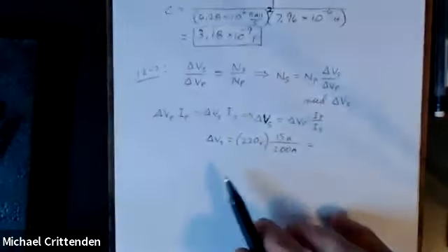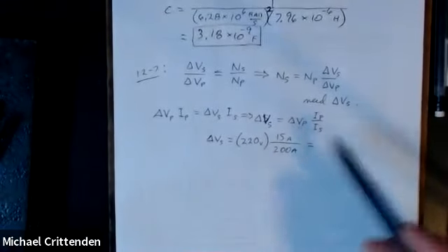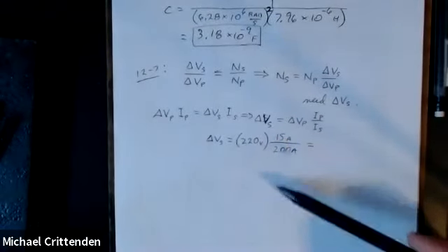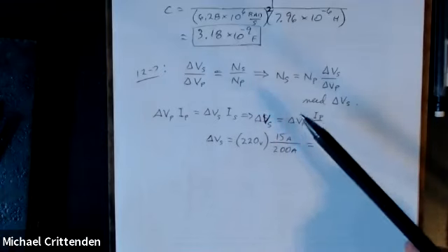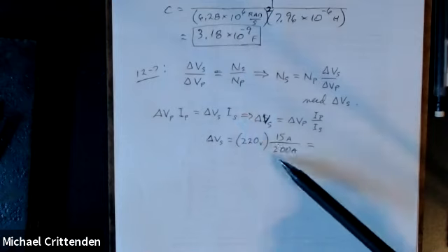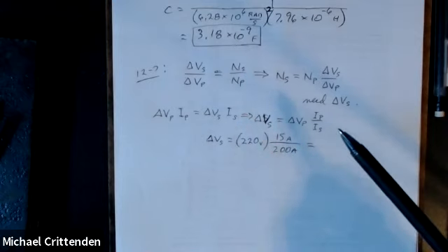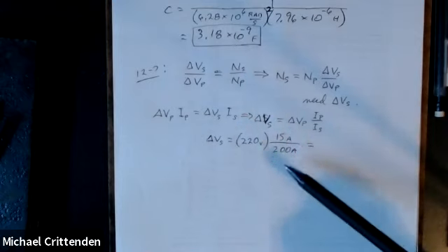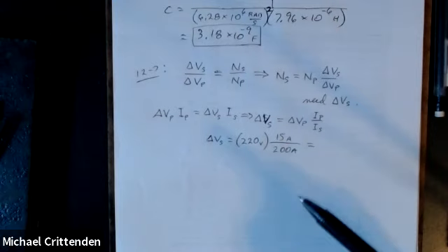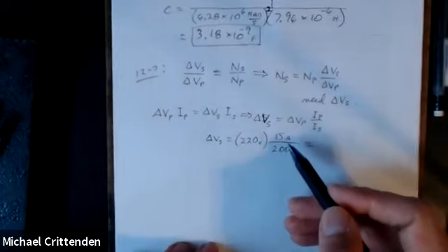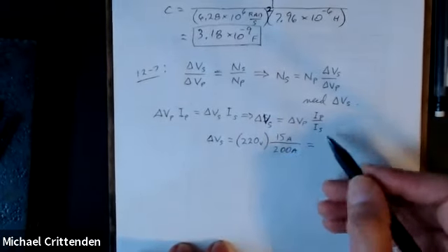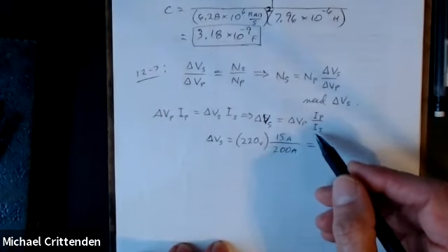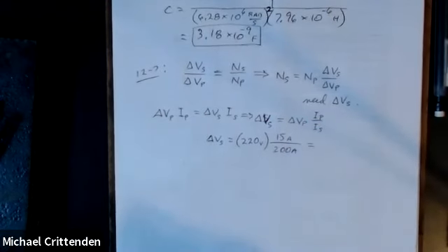Well, one mistake with any problem that involves ratios like this is people getting the numbers mixed up with each other. Keep in mind what ought to be happening. When the number of amps goes up, the voltage should be going down. There's a trade-off between the volts and the amps. So if 15 amps is going to get stepped up to 200 amps, then the voltage should be being stepped down.